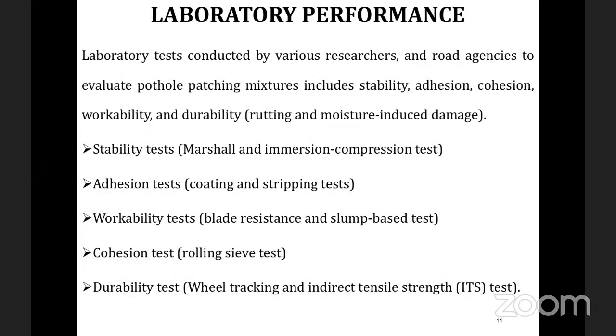Next comes the laboratory performance. There are various laboratory tests that have been done on the pothole patching mixtures. Some of them include stability, adhesion, cohesion, workability, and durability. Rutting and moisture damage are the main things we have to focus on in the pothole patching mixtures.